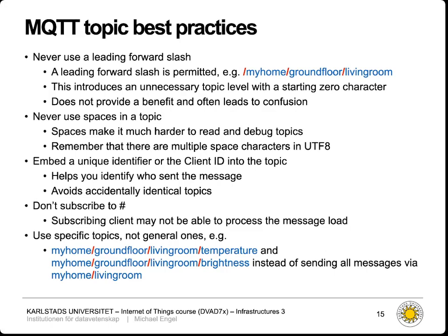Now, when we use MQTT topics, there are some best practices. One of the best practices, first, when you use Unix systems, is that you would usually want to put a leading slash there, indicating this is the root of my messages. You can do this in MQTT, but in MQTT this would imply that the first part of our topic would be the one to the left of the first slash, and that would be empty.